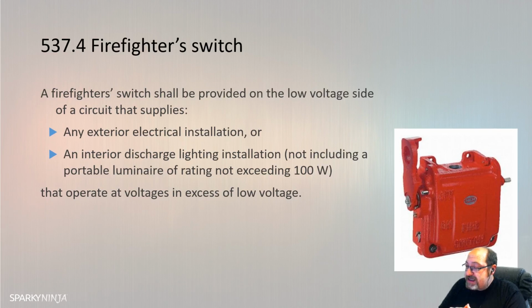The switch should be placed in a conspicuous position, reasonably accessible to firefighters, at not more than 2.75 meters from the ground or the standing point beneath the switch. So they need to obviously get underneath it and knock it off. It will be clearly visible, accessible, and marked to indicate the installation or part of the installation which it controls.